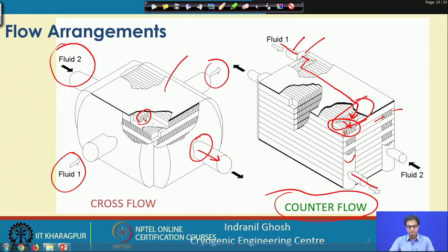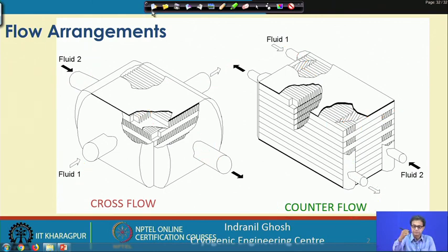We have a very stringent requirement, particularly in the case of the brazed aluminum plate fin heat exchanger, as we have discussed earlier, because the solidus and the liquidus temperature of aluminum are very close, and we need a very stringent temperature control in the furnace or in the dip brazing. I mean, we will discuss that in the later slides.